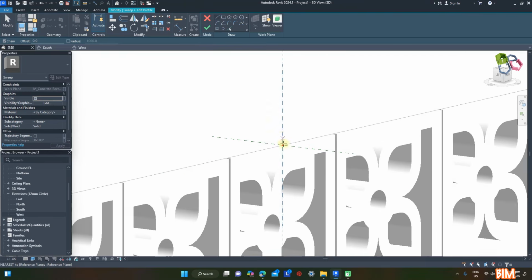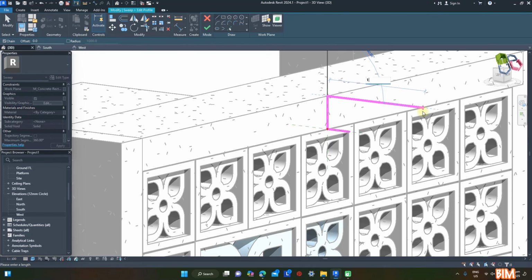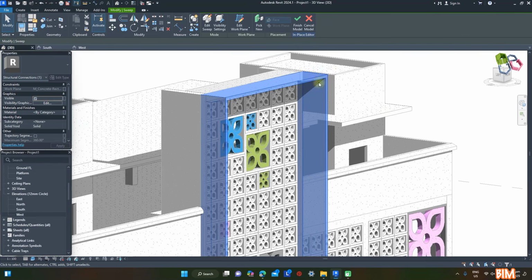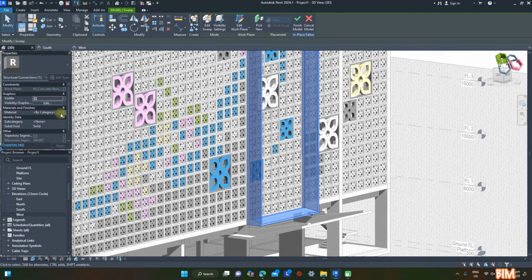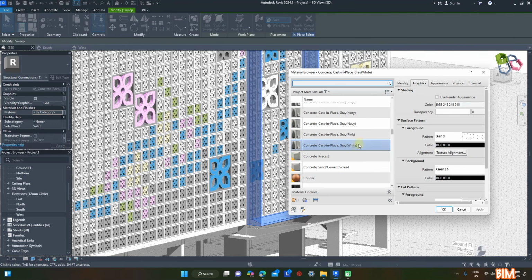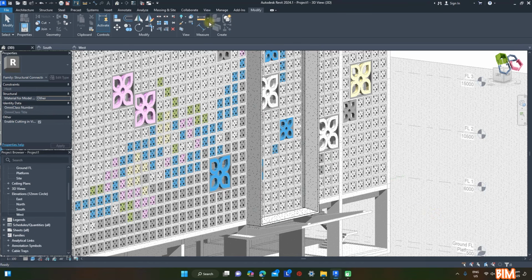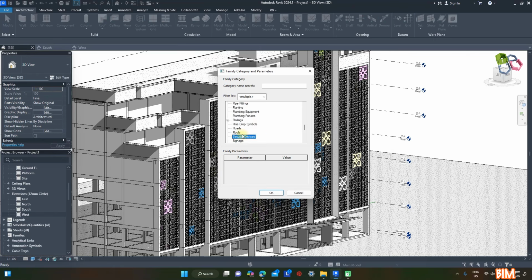The profile position is here. Draw a profile with 400 height, and extrude 1400 mm out to get this shape. Then OK to generate the sweep, and apply white material to it. Repeat for the next large panel on the left with the same process.